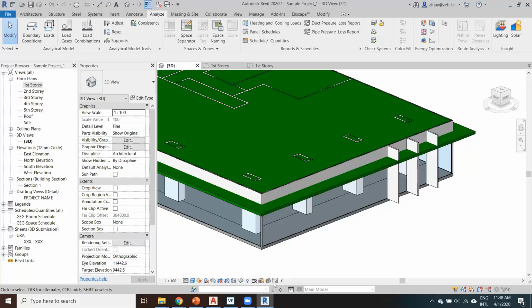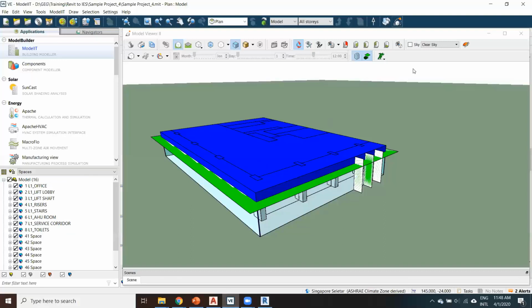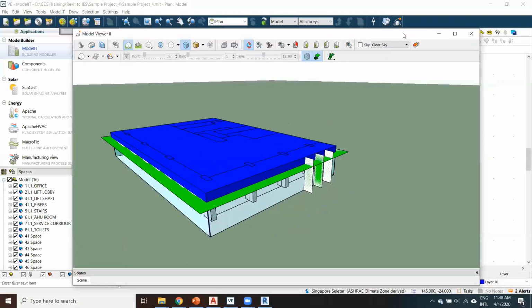And then eventually in IES, as Gene Horn has shown us, you can change the material of the spaces, like the floor of that particular lobby space. You can turn it into a transparent opening in IES, because it's going to present problems when you try to do those spaces that encompass 2 levels. It's going to present more challenges for you, so you can just easily do it in IES.